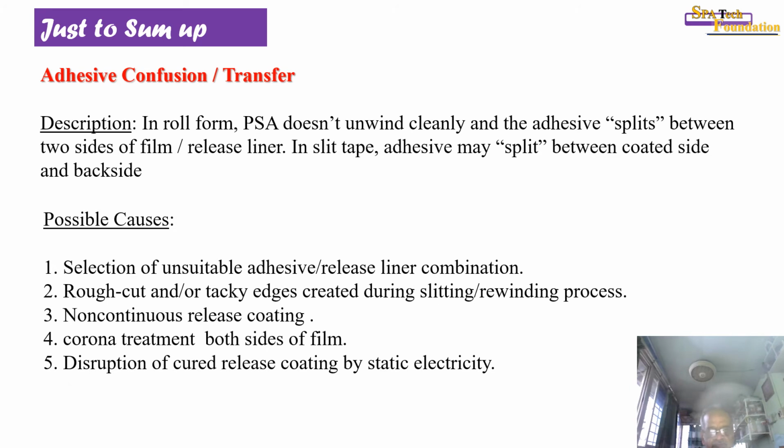The possible causes: selection of unsuitable adhesive or release coating, rough cut and or tacky edges created during slitting or rewinding process, non-continuous release coating on backside, corona treatment on both sides of the film, disruption of cured release coating by static electricity.